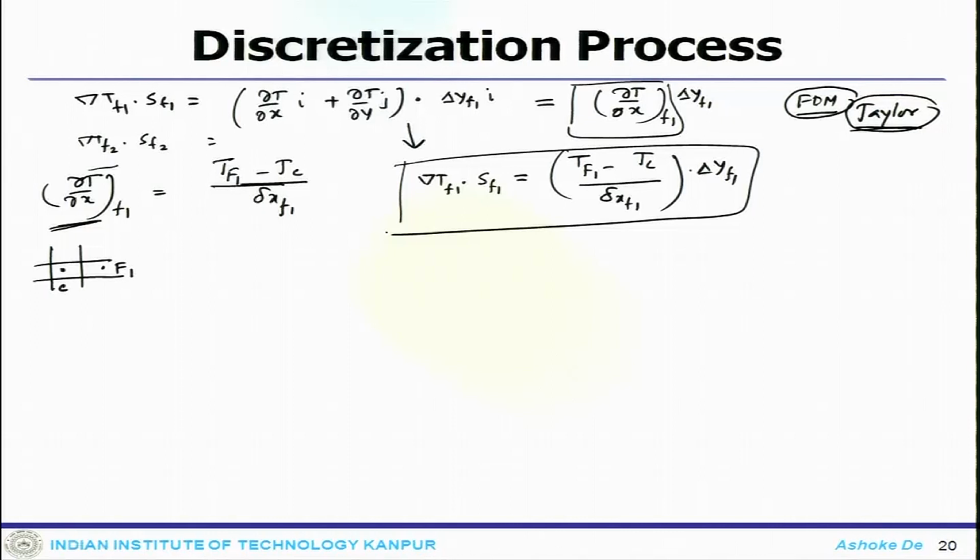Now, if you look at this particular expression, this is very interesting. You started with a partial differential equation, you integrated over the finite volumes, and then finally what you got, at least in one component, is only the information of some algebraic expression. The values you require are some sort of floating point or double precision data. All of this information is only scalar quantity, there is no vector involved, no integration involved. So, it essentially brings down to the algebraic system with all these components.